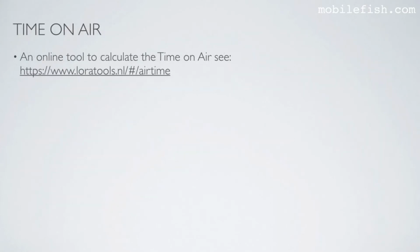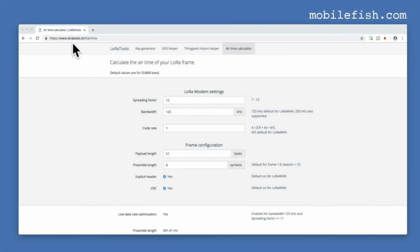There is an online tool to calculate the time on air. This web page. Let's set the spreading factor to 12. The bandwidth is 125 kHz. Set the code rate to 1. That's the default for LoRaWAN. Change the payload to 10 bytes. Set the preamble length to 8 symbols. That's the default for the AU868 band. The explicit header and the cyclic redundancy check are both enabled for LoRaWAN.